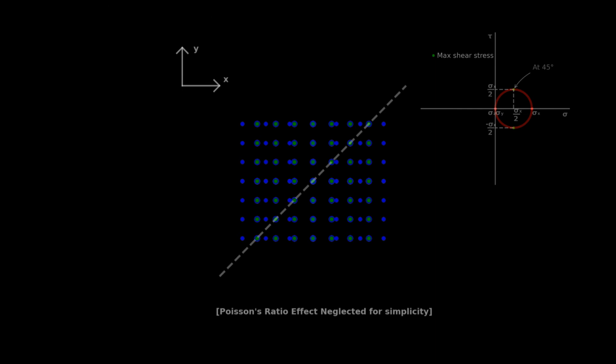Let's first apply the two shear stresses, half the magnitude of sigma x at 45 degrees. Next, we apply the normal stresses at half the magnitude and at 45 degrees. We have arrived at the same end state. If we want to know the combination of stresses at a different angle, for example 30 degrees instead of 45, we simply rotate the points in the Mohr circle by twice that angle, or 60 degrees, and read the values off the graph. Now, Mohr circle is looking like a rather useful tool.